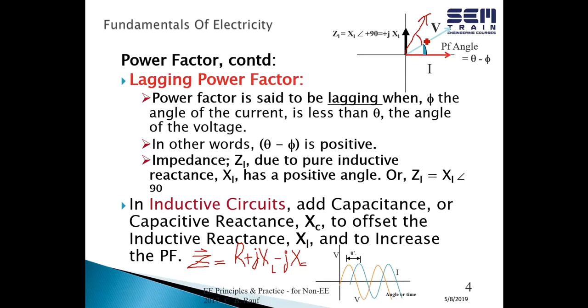So anyway, now the current has surpassed the voltage by 30 degrees, but cosine doesn't care whether the angular difference is negative or positive. Either way, when you take the cosine of 30 degrees, you'll still end up with 0.866 or 86.6% power factor. So you had achieved unity, a perfect utopian scenario, but then as the load dropped out, your system is overdosed with capacitance, and the power factor is back down to 86.6%. And to avoid that, sometimes you use automatic power factor